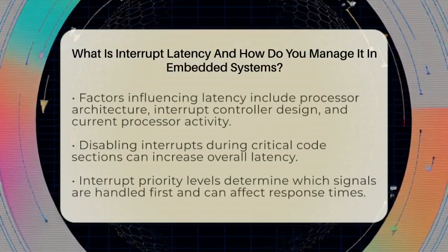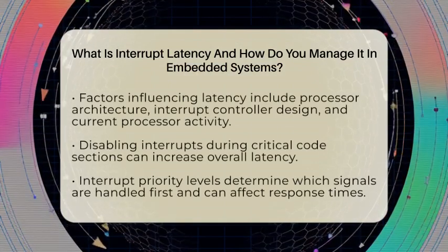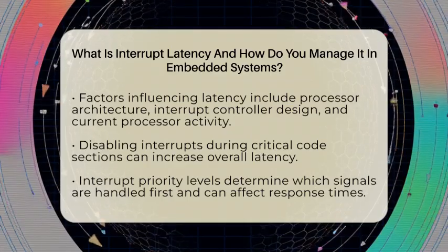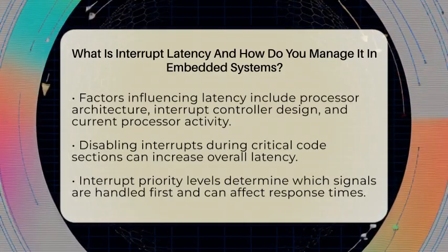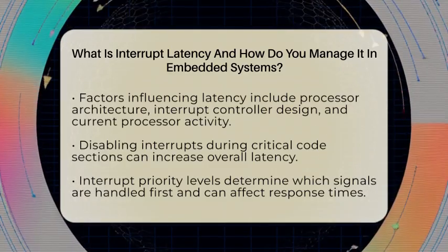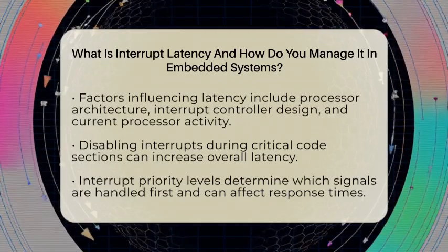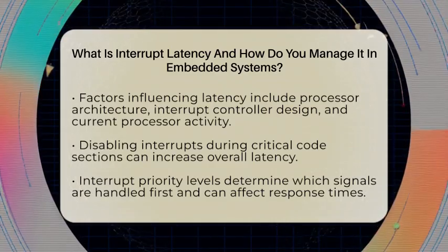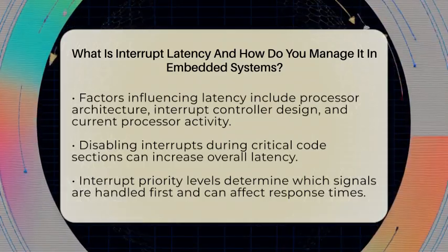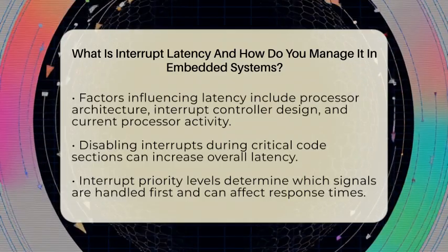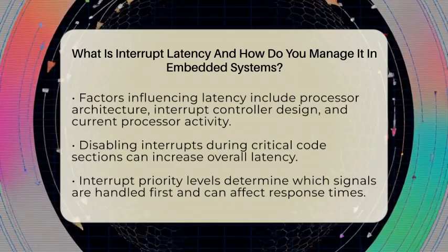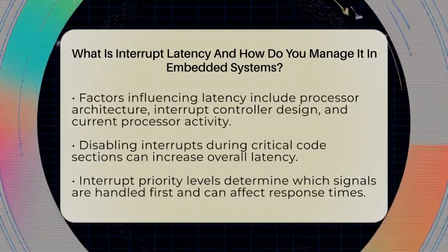The length of this delay depends on several factors. First, the processor architecture plays a role. Some microcontrollers are designed to acknowledge interrupts faster than others. Next, the interrupt controller, which manages multiple signals, can add some delay depending on how it's built. Another factor is what the processor is doing at the moment. If it's busy executing a long task, it might take longer to respond to an interrupt request. Also, if the system disables interrupts during critical sections of code to avoid conflicts, that can increase latency.